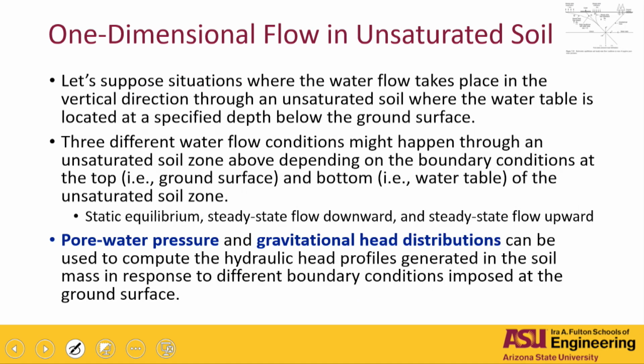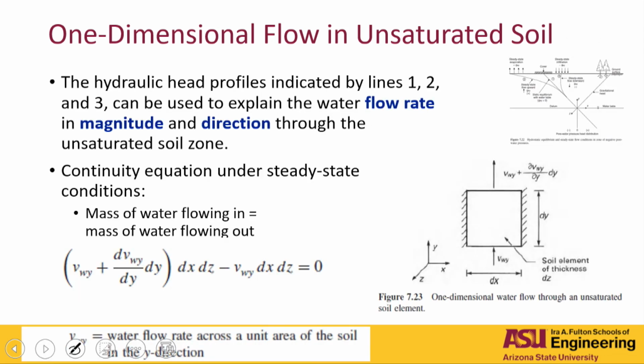All right, so those two can be used to compute the hydraulic head profiles generated in the soil to different boundary conditions that you're going to have in the field. Okay, so these lines, as I said, can explain the water flow rate, the magnitude and the direction through the unsaturated soils.